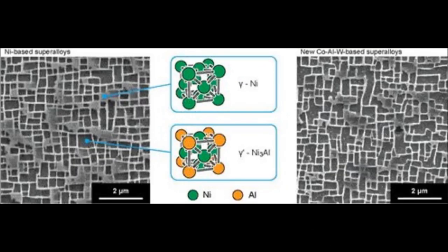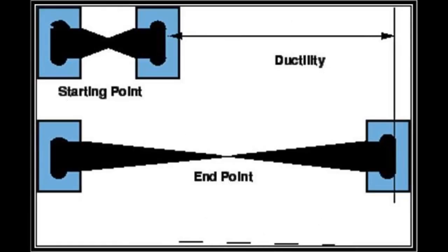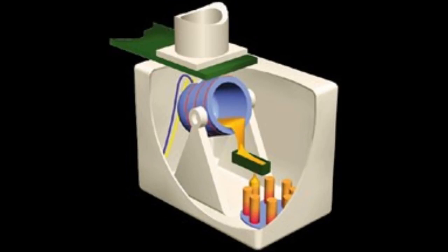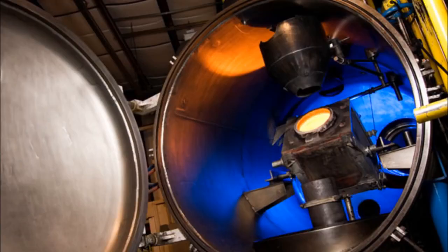The turbine blades are nickel-based, with other materials mixed in. The air melting process used to create the superalloy blade included aluminum and titanium elements. This strengthened the material, however, creating low ductility. For a blade to work successfully, it needs to be a combination of strength and ductility. That is when, in 1953, the innovation of vacuum induction melting, or VIM, made the jet engine what it is today.